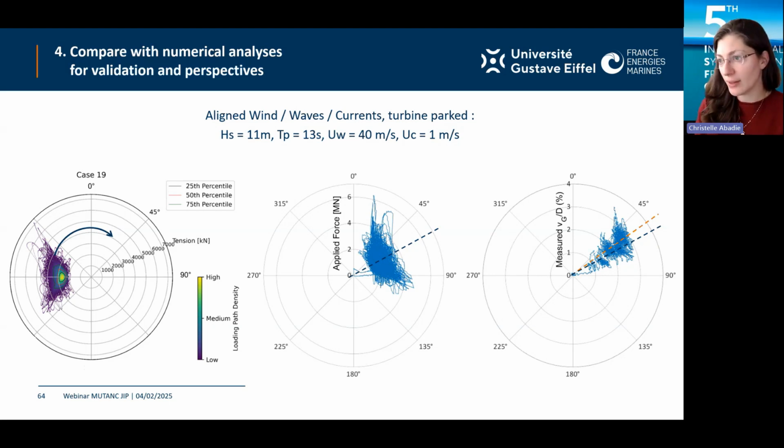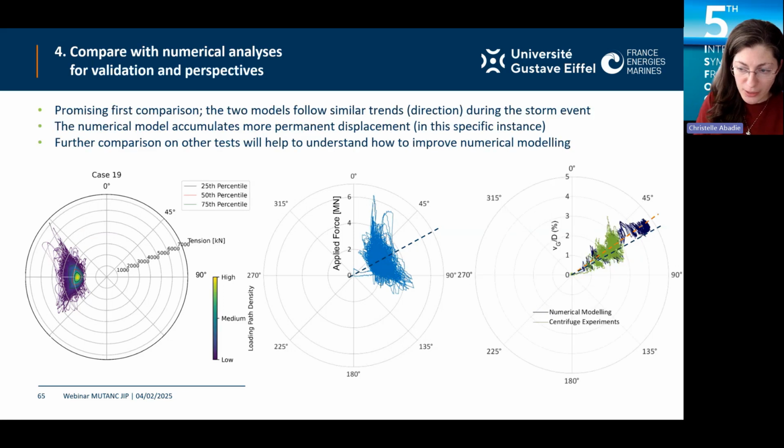So what does that tell you? Is that our simplified load sequences are pertinent and relevant to understand the pile behavior properly and in a rigorous way. And the conclusions also pertain to more complicated load sequences that may not be as tidy as what we have in the previous cases. And now in the next slide, I show you the comparison with the numerical analysis.